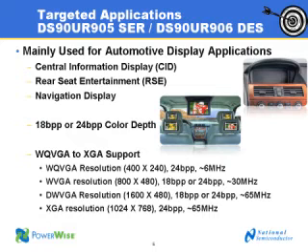One of the big changes, like Sue had just mentioned, is that it supports both 18-bit and 24-bit color depth. And the higher color depth really makes for a better picture. And finally, it supports much higher resolutions than the older chipsets, up to the 64 megahertz pixel clock. So some of the resolutions that we support include the WQVGA, which is a 400 by 240, all the way to the XGA at 1024 by 768.